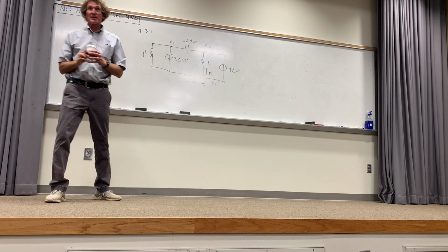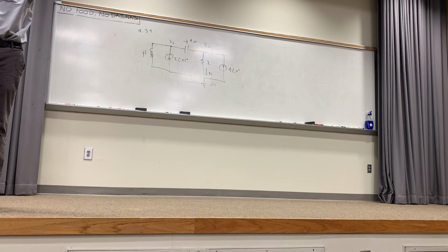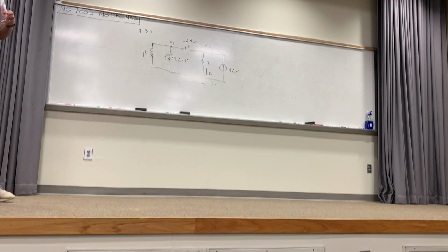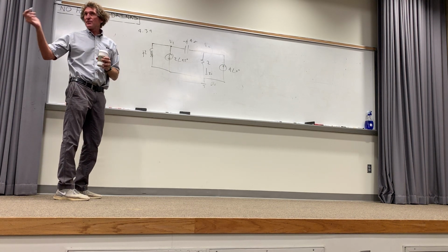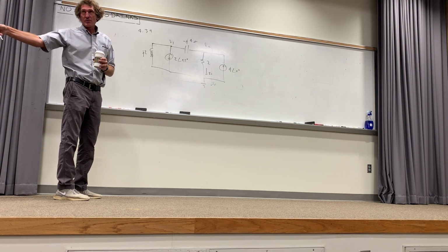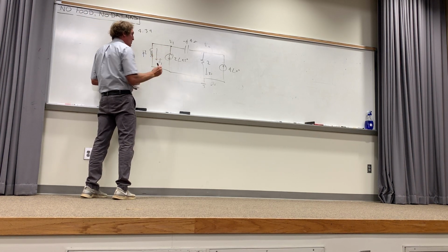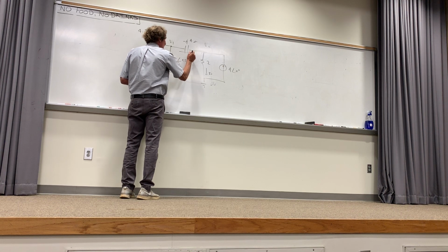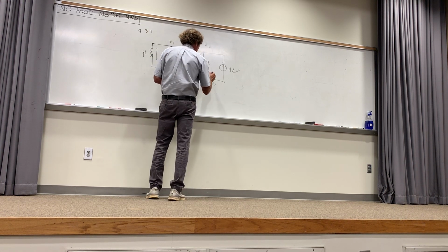Now you're going to be expected to put those in. I'm not going to, unless if I do supply them, all right, then you'll use what I indicated in node values for V1 and V2 if I ask to solve those. But generally speaking, you would put those in for say nodal analysis. Now after that, you find all the currents into equal all the currents out of the node. There's the first node. I'm going to have a current here, call it I1, and I'm going to have a current here, I2. Second node, I've got another current, that's already labeled as I0.